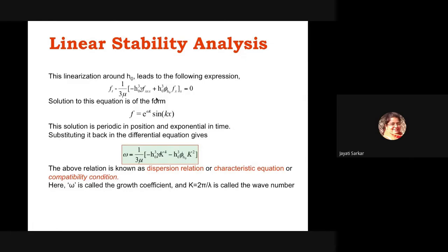This is a fluctuation on top of the uniform thickness, and we perturb the initial surface with this type of disturbance and want to see whether this perturbation grows or not, right? So when we put this function in this equation and we get rid of the higher order terms of epsilon, because epsilon is itself a very small quantity,